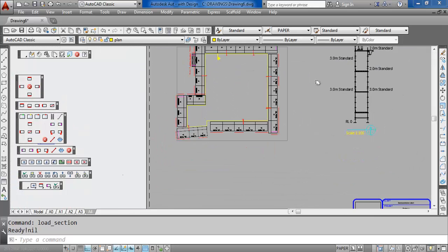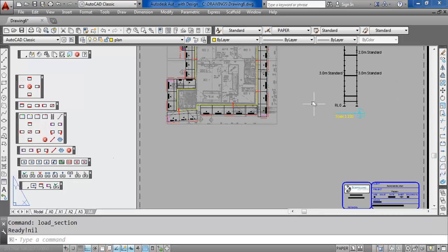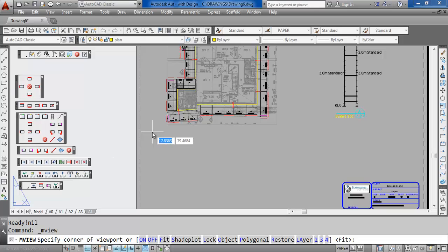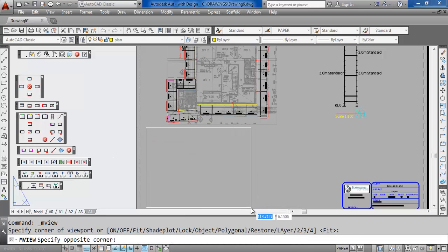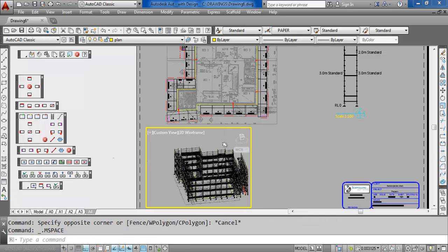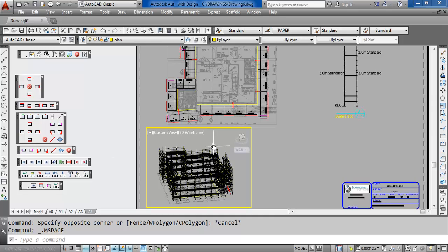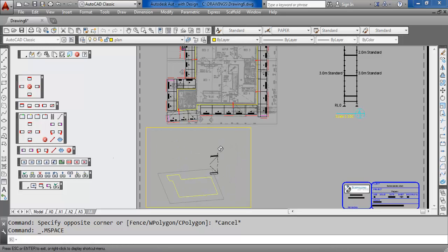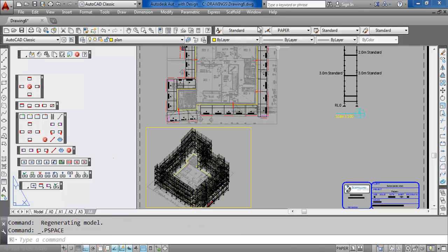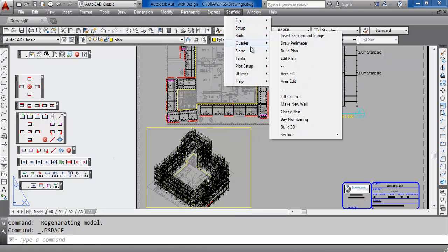section A. Then we can actually put our 3D drawing on this sheet as well by creating a view. And this view can be anywhere we like, so we can go in there and pretty much zoom in to any particular area or scroll around on any angle that we like, just like we did before. Like that. And we can create another view of the 3D.